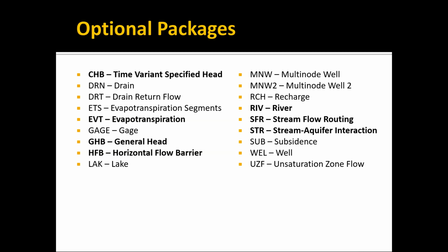You can have a well screen span multiple layers, and it automatically distributes how much water comes from each layer based on the transmissivity of the layer and the heads in the layer. Something that you just can't do with the well package.